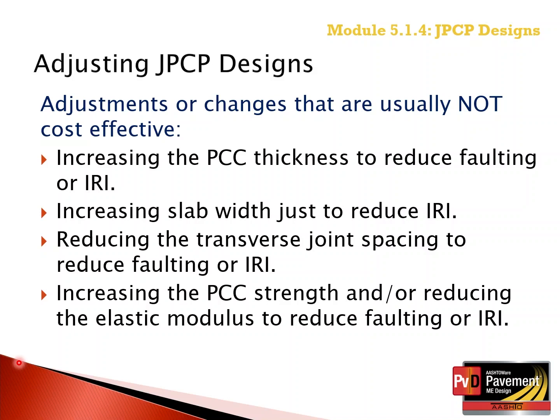In other words, the distress sensitivity to those values is low. Thus, the designer should select only those variables that have a significant impact on reducing the distress not meeting some criterion established by the designer for the specific design.